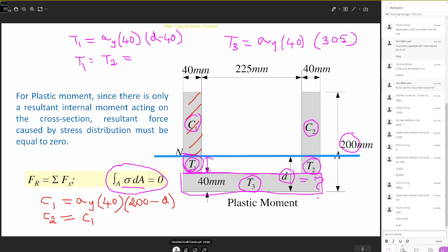Okay. So we can imagine the neutral axis on the section. With respect to the neutral axis, we can identify the zones of compression and zones of tension. So we write the compression acting above the neutral axis and the tension acting below the neutral axis. And the expression says the sum of sigma into dA is equal to 0.